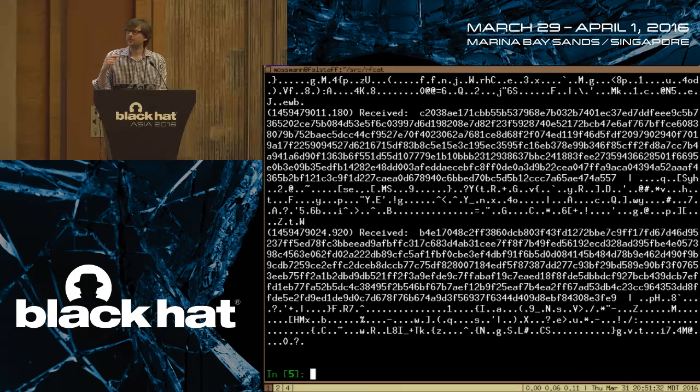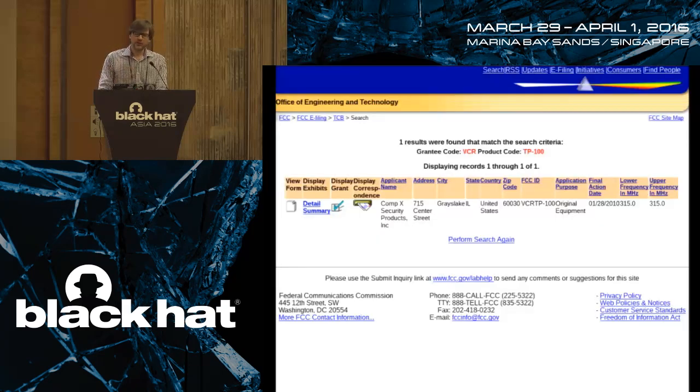The reason it's not doing anything, probably the main reason, is, well, there are two reasons. One is that it's expecting that a packet starts with a preamble. By default, the wireless transceiver chip that's on the Yardstick 1 expects to see a preamble of alternating symbols at the beginning of the packet. So it's expecting to see on, off, on, off, on, off, on, off, or 1, 0, 1, 0, 1, 0, 1, 0. And we don't actually have that.